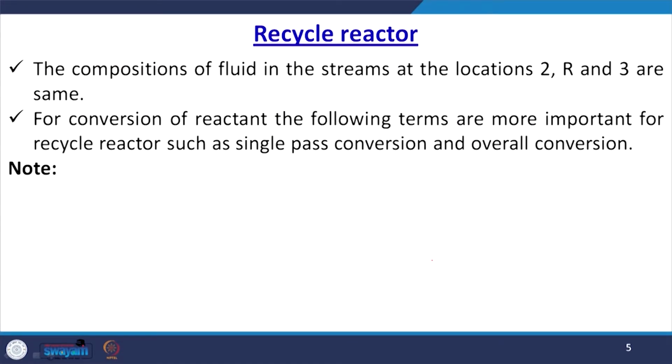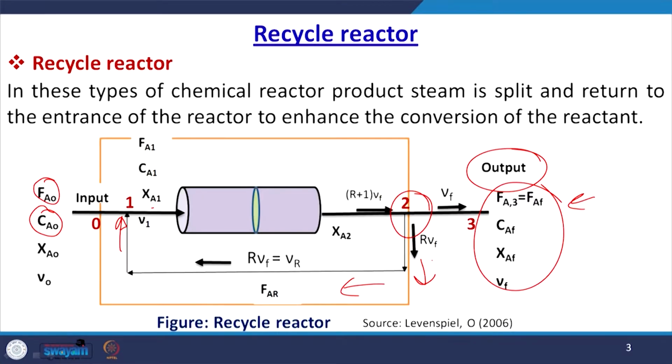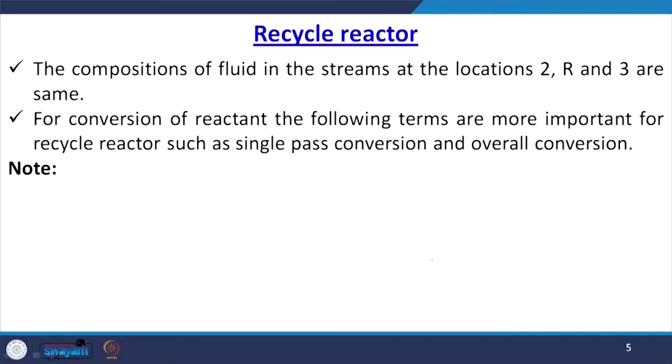Now, when we talk about the composition of the fluid in the stream, usually situated at location number 2, then R and 3 are the same. The conversion of the reactant can be given in various terms, and they attract more important aspects comparatively in the recycle reactor system. And sometimes you may need to address things related to the single pass conversion and overall conversion system. Now, let us have a look at the single pass conversion.